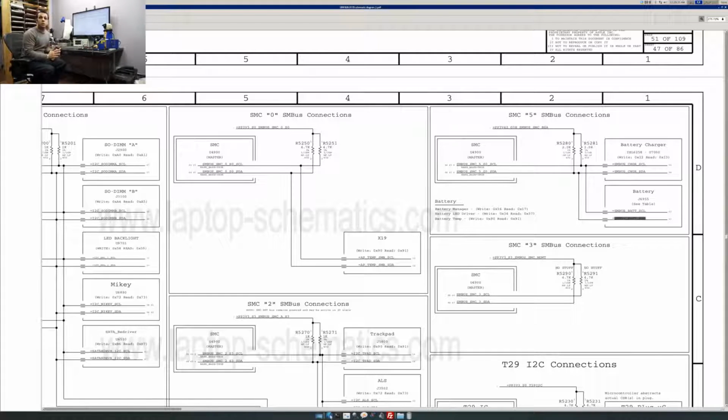Again, if you see that the pulses are only going up to a maximum of 2.6 when the data line is being created from a 3.4 volt power line, it never goes higher than 2.6, is something pulling the line down? I have had that happen before. I had a webcam connector that looked perfect that was pulling a sensor line down to 2.6, and as soon as I removed the damn webcam connector, I was up to 3.4 and nothing was running slow anymore. So these are all things to think about.